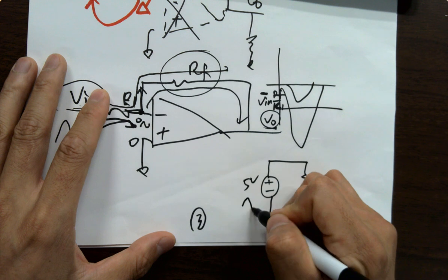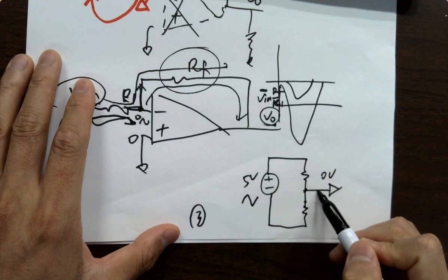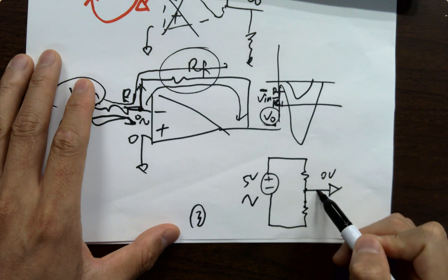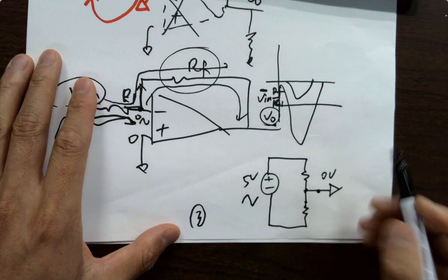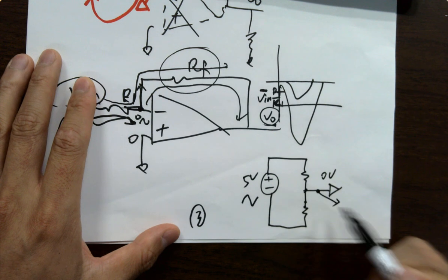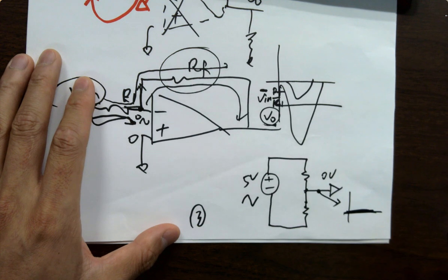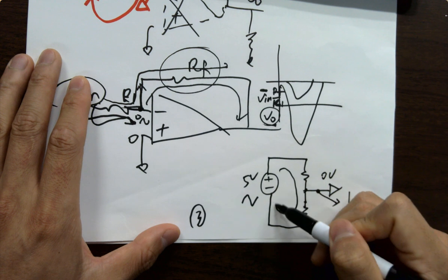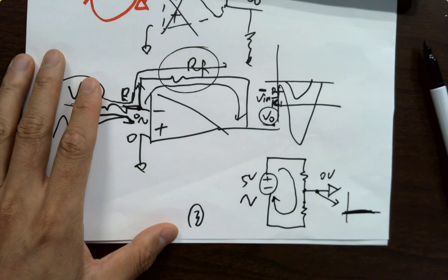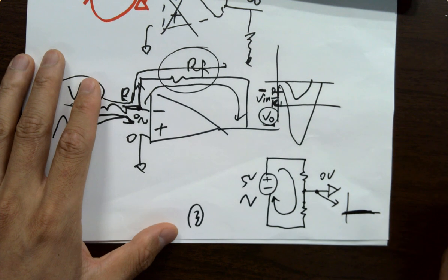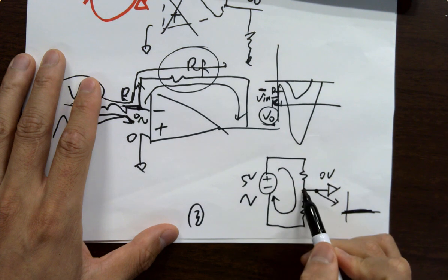However, if you inject a sine wave here, what's going to happen? Are you having a sine wave here? It's grounded. Okay? Which means if you probe it, you are not having any voltage. It's going to be 0, absolutely 0 volts. But do you have current? You have current. You still have current going through it. You just ground this point as a reference voltage.